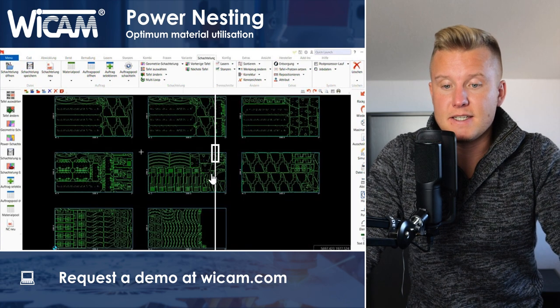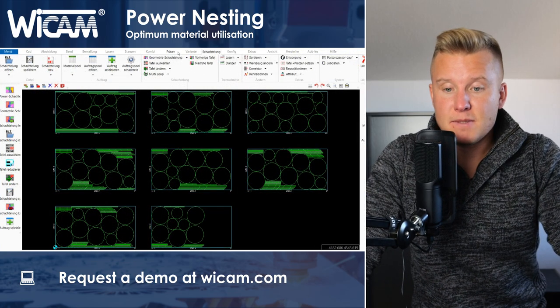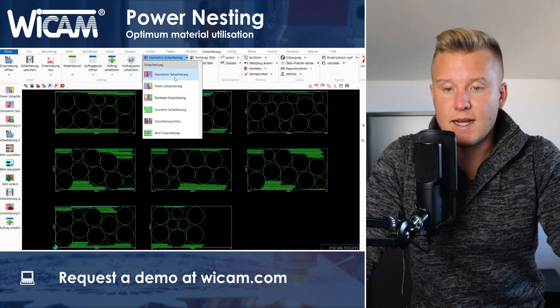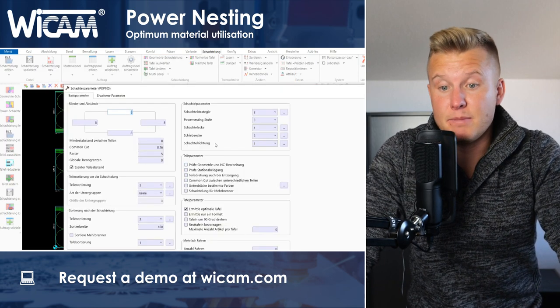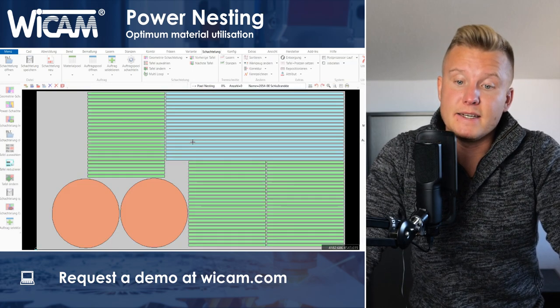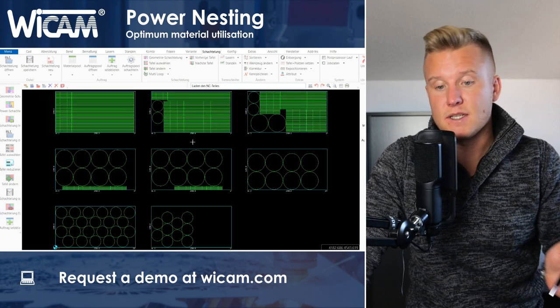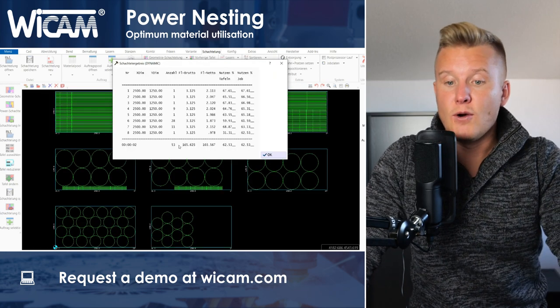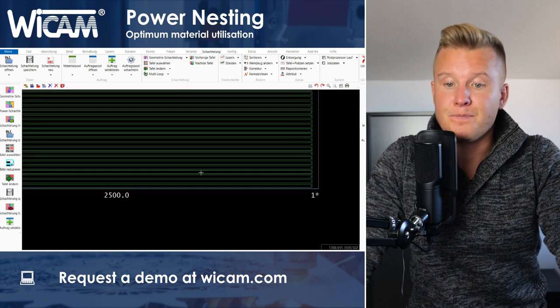But I would say, before we get into the whole topic of power nesting, let's take a look at what a conventional nesting routine does. Because a conventional nesting routine is available as standard in virtually every programming system, where you can nest your parts on the sheet metal according to certain specifications. You can either say, I want to nest the parts from left to right, or I want the large parts to be nested first and then the small parts.